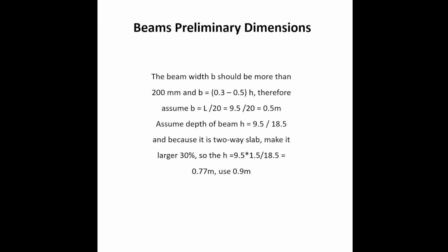Also, we have another two beam groups, which is for the circular cantilever, that we will choose 0.4 by 0.6 meter dimensions for the beam because it has a lot of torsions. So we need also to add an inclined beam, as we will explain in the AutoCAD.